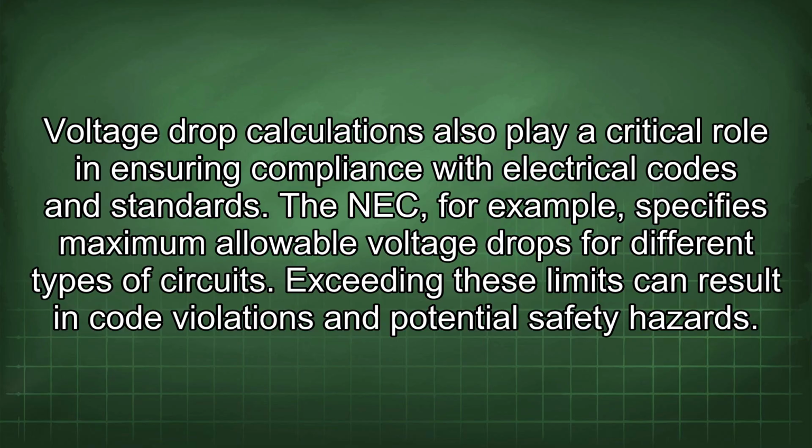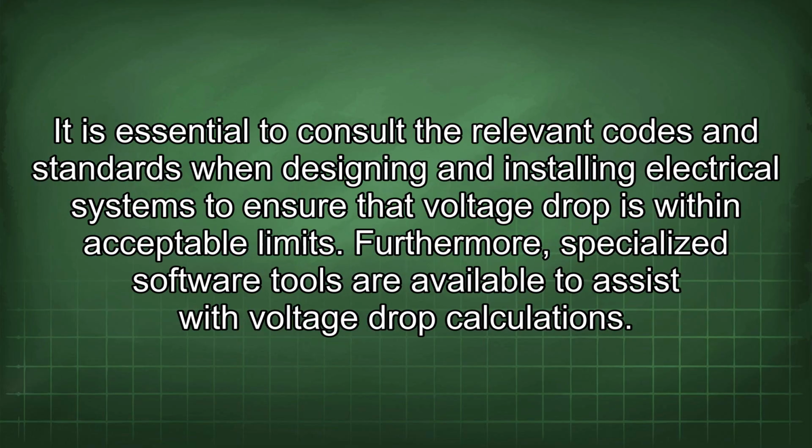The NEC, for example, specifies maximum allowable voltage drops for different types of circuits. Exceeding these limits can result in code violations and potential safety hazards. It is essential to consult the relevant codes and standards when designing and installing electrical systems to ensure that voltage drop is within acceptable limits.